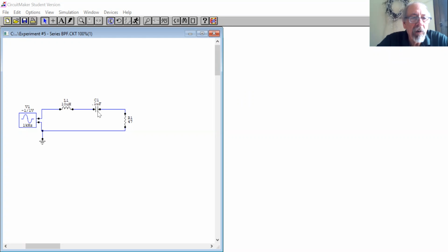The capacitors we already talked about in a prior experiment, at low frequencies, this thing will have an infinite resistance or reactance to the AC signal. The inductor at low frequencies will have low or zero reactance to the AC signal. And then they flip. As we go to real high frequencies, the capacitor acts like a short, the inductor starts to act like an open.